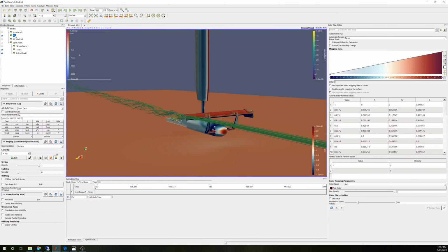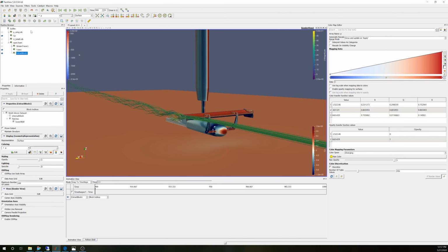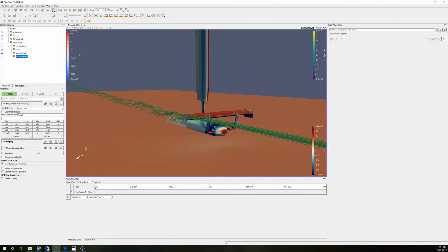How we modeled the tunnel is based on how they recommended. ARC also does CFD, and they use Elements, which is based on OpenFOAM. It looks like pretty awesome software. It's basically a GUI to OpenFOAM, and then they have their own meshing and things like that that are different from the OpenFOAM variety. It was developed with ARC and another company called Ingus, I believe that's how you pronounce it. This is how they recommended setting it up, like tunnel size and everything like that.